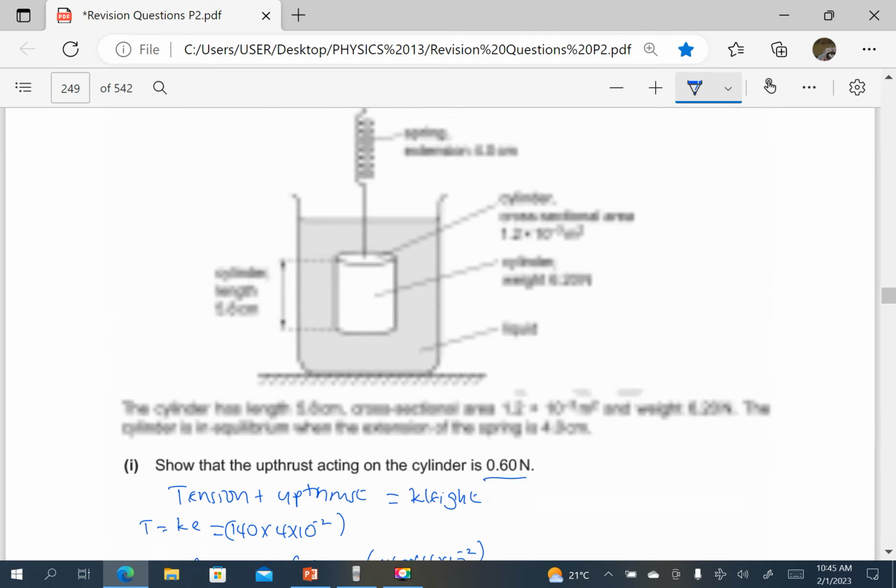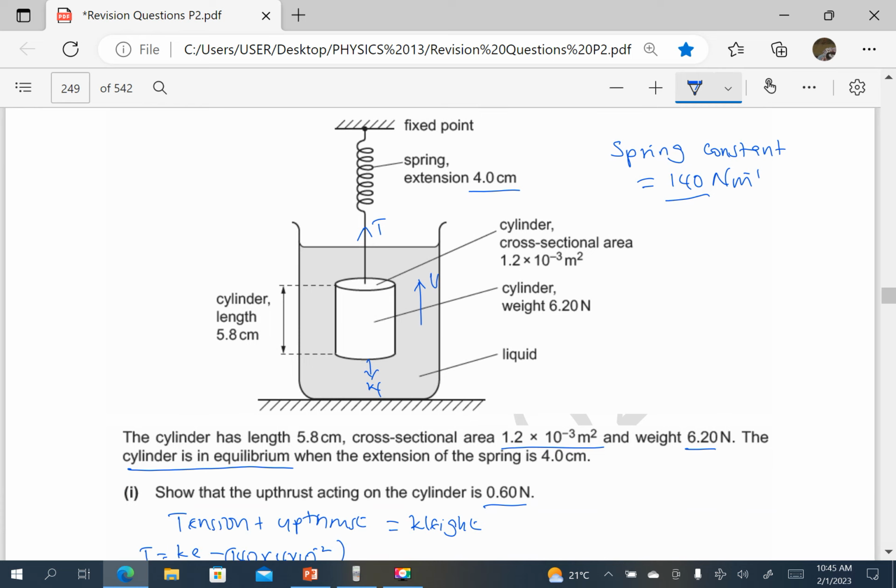What will be the change in h? If the pressure at the bottom is due to the height h2, then the pressure at the bottom, which I'm going to call P2, is equal to h2 times density times g. Then the pressure at the top is going to be P1, and P1 will be equal to the height h1.